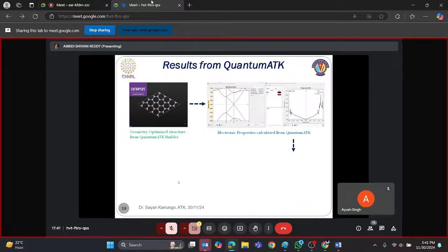So once these properties are realized, the density of state profile can be utilized under the mathematical framework as shown here. This is used to determine the excess charge density as well as the quantum capacitance profile of graphene.